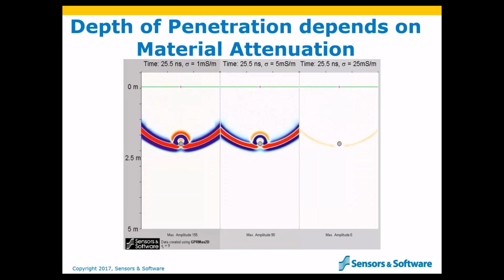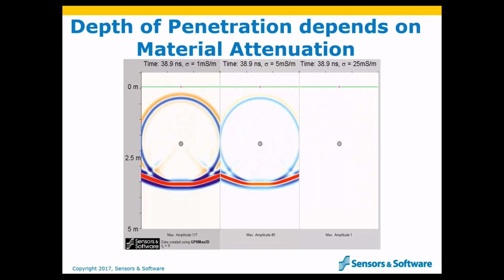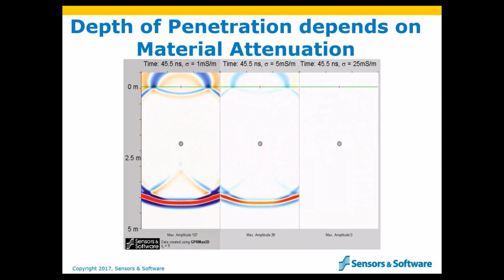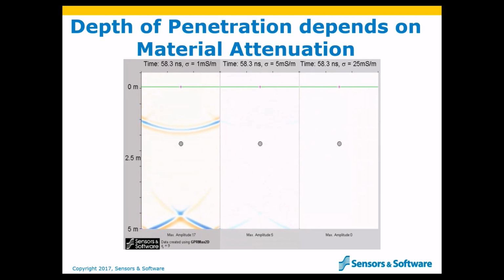One of the best materials for GPR that a lot of you will know is sand, and this is kind of shown on the left side of this image, because sand generally has low electrical conductivity. Signals travel deeper before getting absorbed.